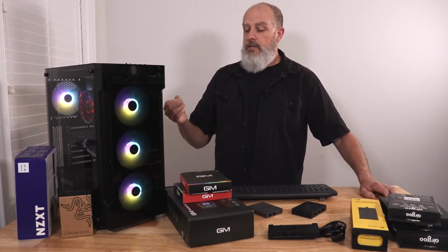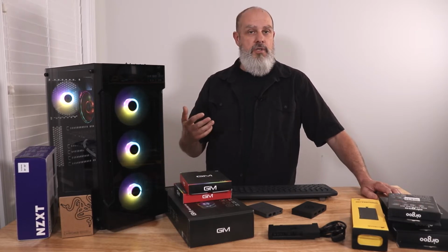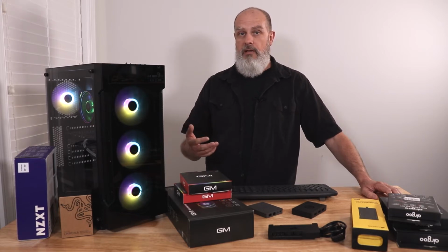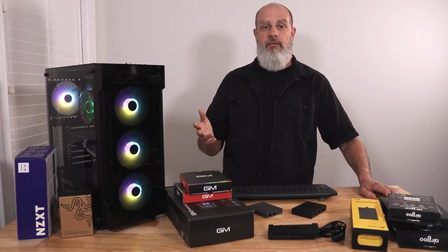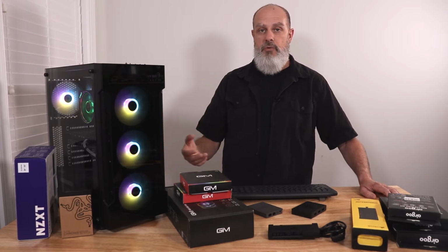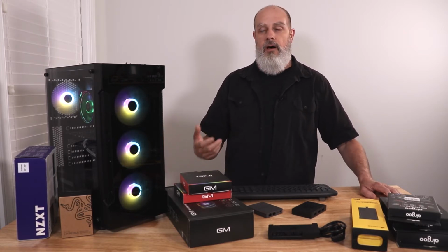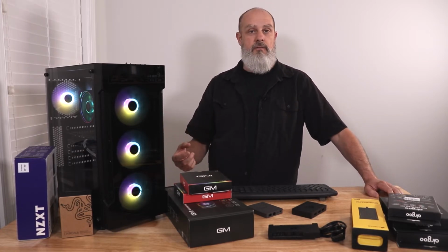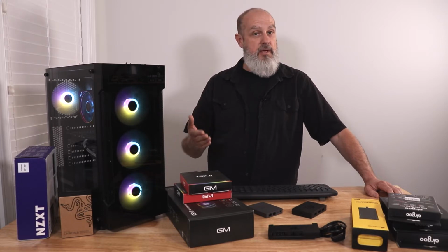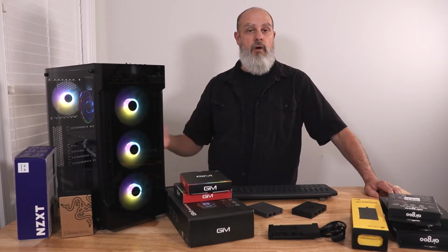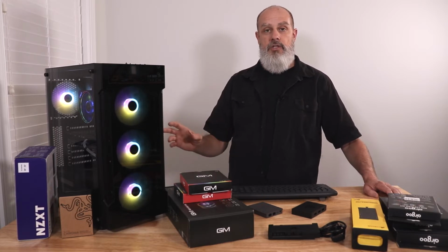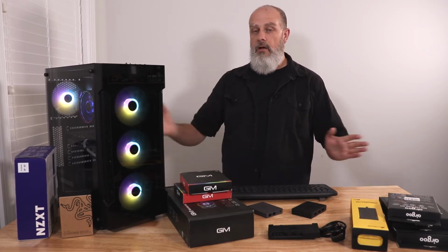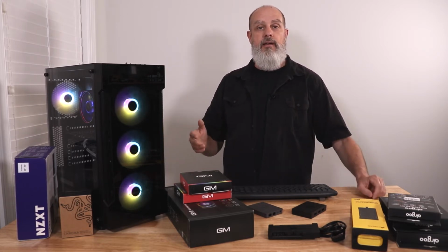And so the next set of terms that you're going to see thrown about is ARGB or addressable RGB or digital RGB. I've seen all three of them used. Sometimes the header on your motherboard will show ARGB, and they really all mean the same thing. What it means is that you can control each LED individually. Because of that little chip that is embedded in each one, you can talk to that chip individually, and you can set a different brightness or a different color all across the strip. So you can talk to every light individually.